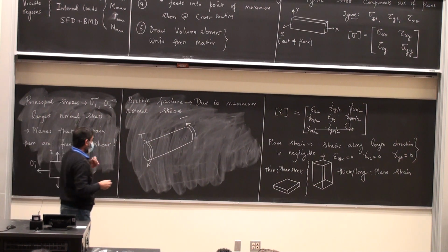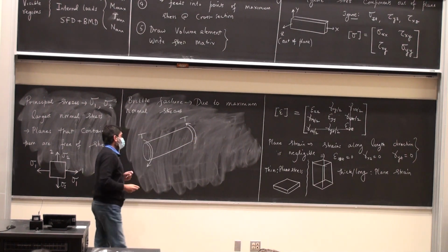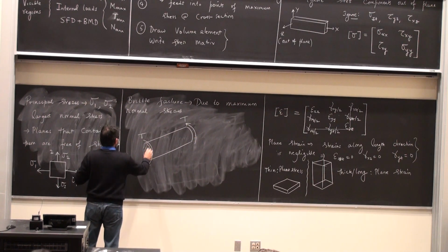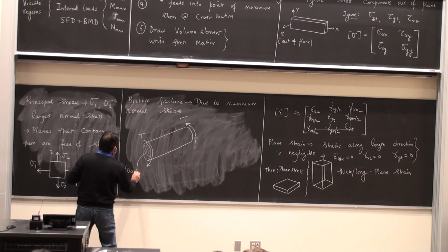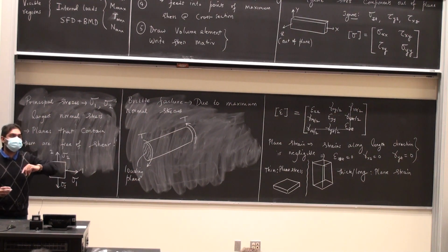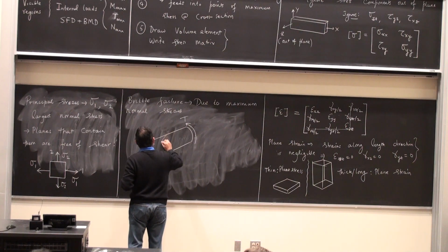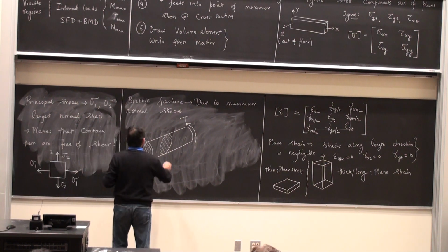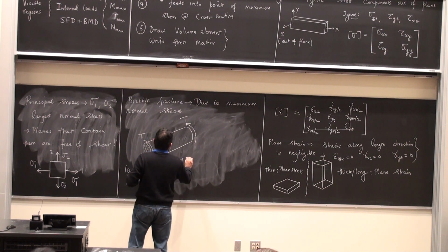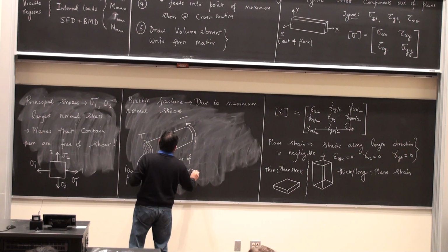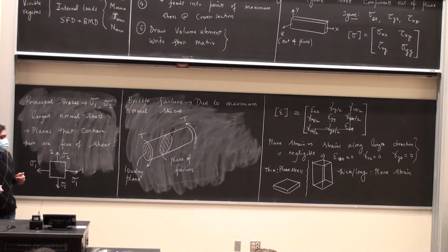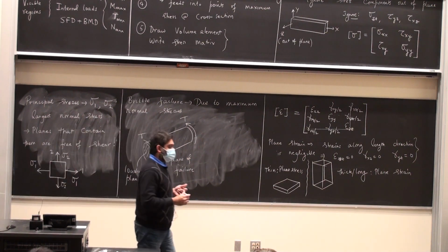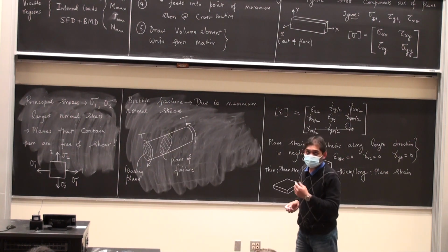And so we want to figure out, okay, it fails, right? So perhaps the plane of failure, this is the plane of loading. The plane of failure is inclined, as you saw. So this is the actual plane of failure. We want to figure out what this inclination is, and we also want to figure out what is the largest stress value that causes failure.